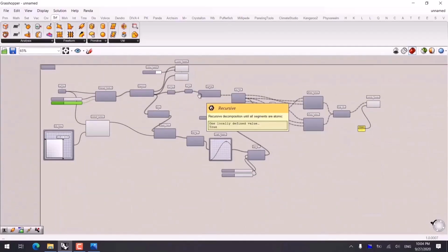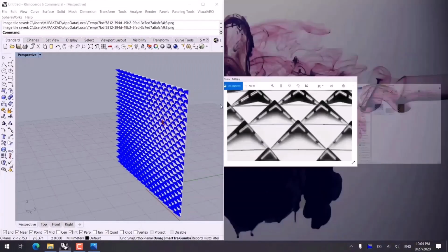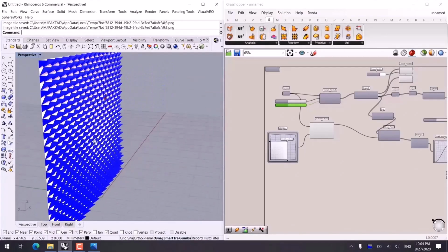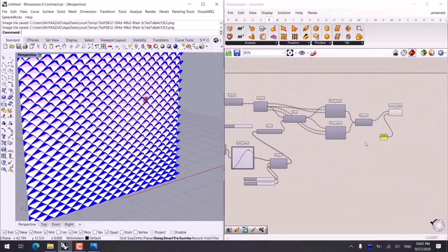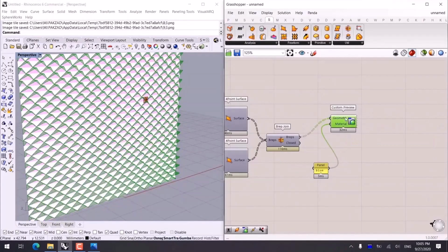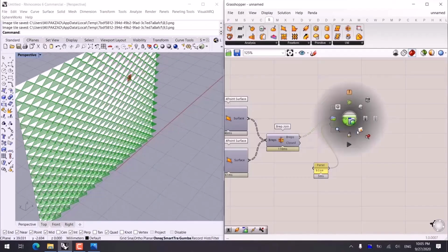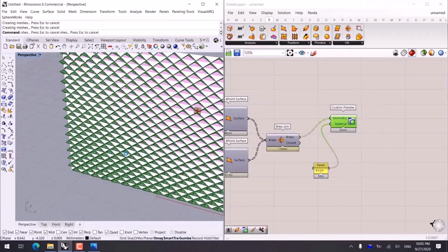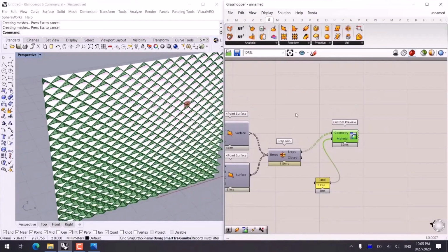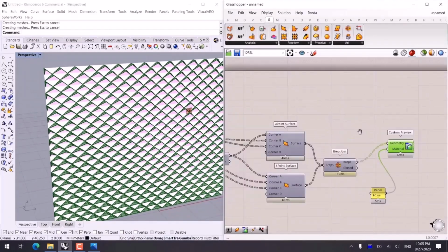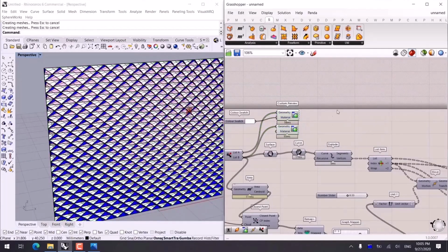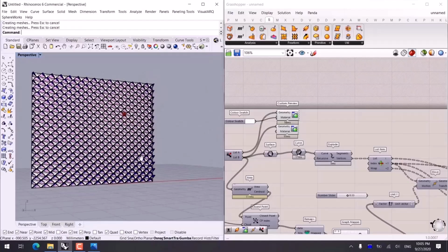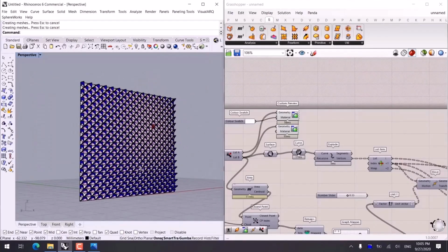The next point that you may find practical is to prepare a preview of the project from Grasshopper for ourselves. To do this, bake the panels in Rhino. We select them by custom preview, right click, bake. Check it out. And then after baking the objects in Rhino, we can select these two and bake them in Rhino.